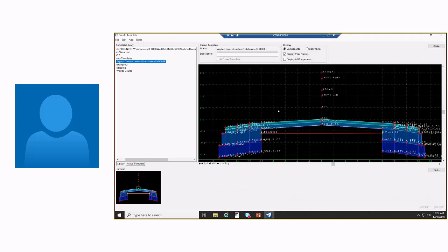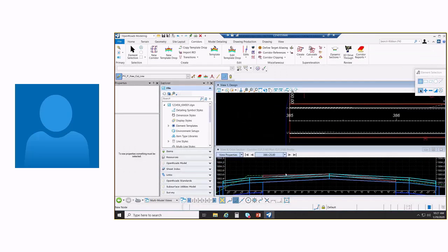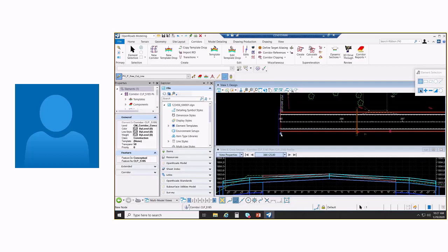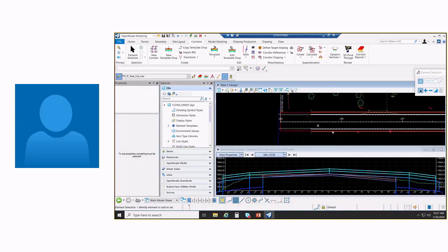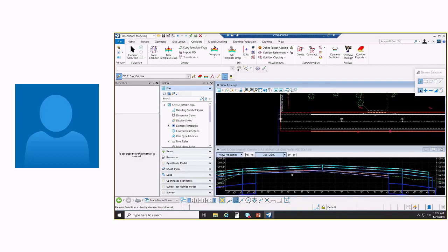Another thing on this one, yeah, there's a pavement planing option here. So if I would put it up on the proposed profile, that would have made more sense where that is located. So I should be able to just change that here on my properties, and instead of using the active profile, I'll use that proposed profile. There we go. And you can see it adjusted the starting limit because my proposed profile didn't start until 385 plus 50. So that makes a little more sense with the way I had that defined.